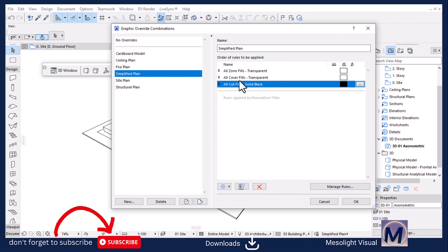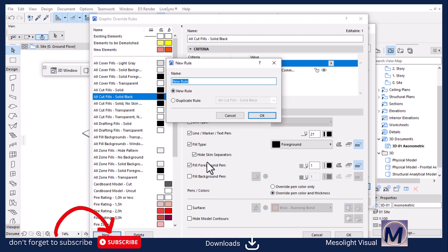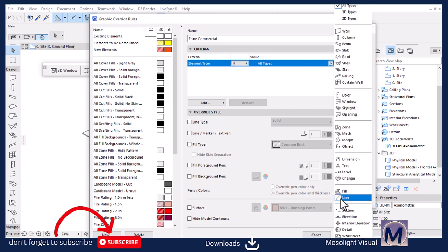And then we're going to create an independent rule for our commercial plots. So let's do that. We're going to go to manage rules, and then go here and say new rule, and we're going to name it zone commercial, then hit OK. Element type is going to be the zone.